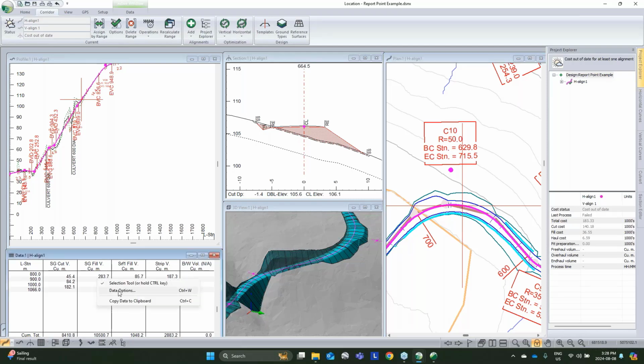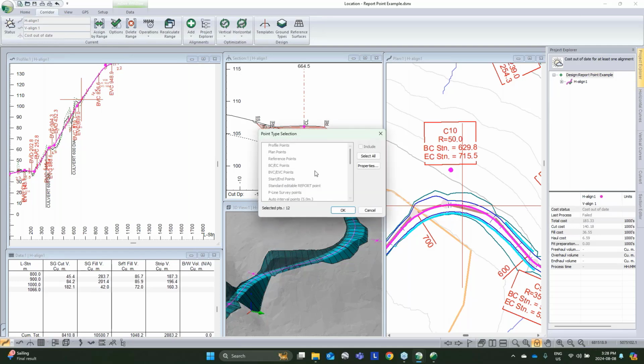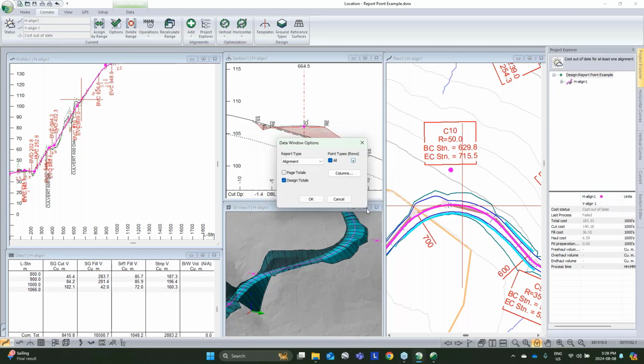And then lastly, related to report points, throughout the software, aside from just creating that model, we use those report points to control how we're reporting things. So in this case, my data table is being set to report points every 100 meters, and then at the start and the end points. And then similarly, if we're doing a multi-plot and we want to report our cross sections or control our pagination settings, it all comes from in there.